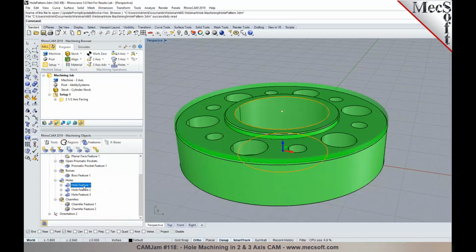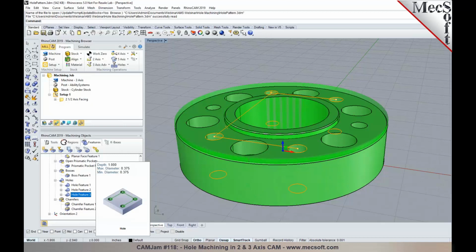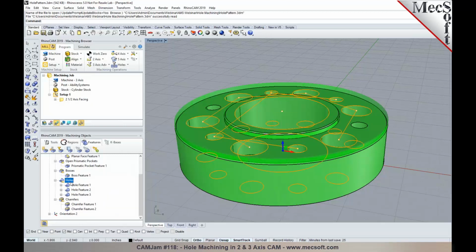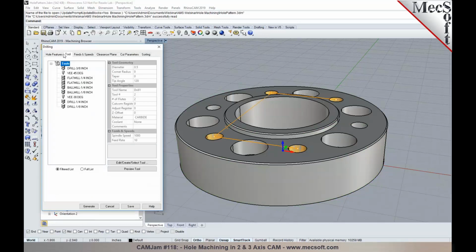As you hover and select one of the features, it gives you information about the depth and the min and the max diameter for each of the features that were identified. If you're working with solid surface geometries and you have prismatic parts, you could take advantage of feature detection. Once you have these features detected, you can automatically do what is called feature machining. In this step, it automatically selects those features and creates the machining operations, and you can edit the operation to pick a tool that's most appropriate in here.